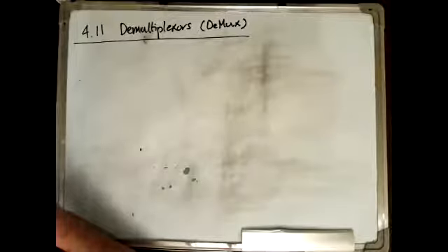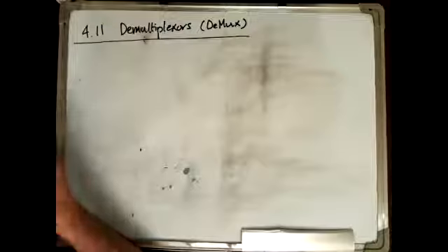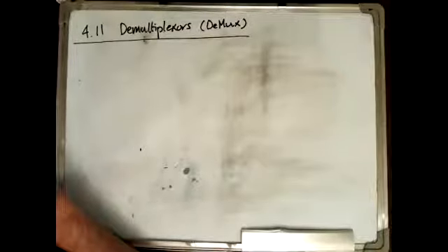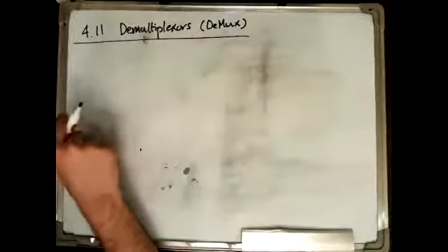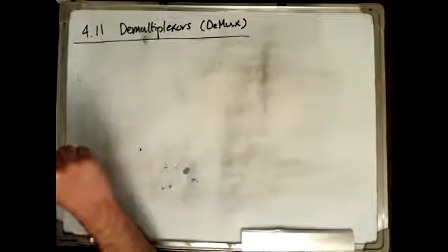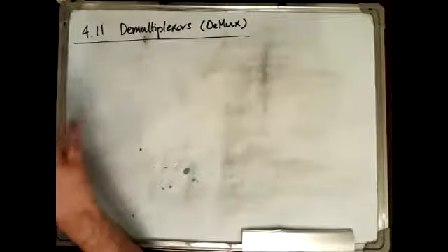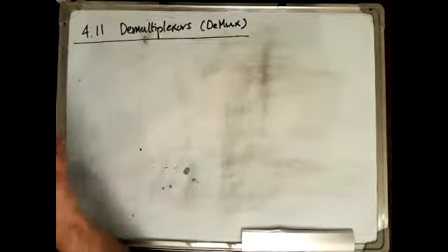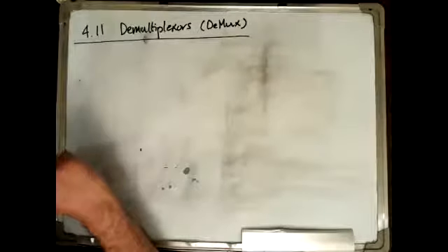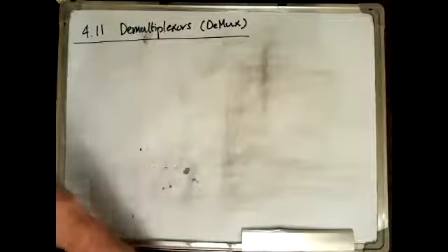Functional blocks, we said, are combinational logic circuits that are already designed for you, available for you to use without redesigning them. And the demultiplexer has a relation similar to what we discussed when we talked about the decoder and the encoder. The decoder and the encoder reverse the operation of each other. The same thing, the demultiplexer is a circuit that reverses the operation of the multiplexer.